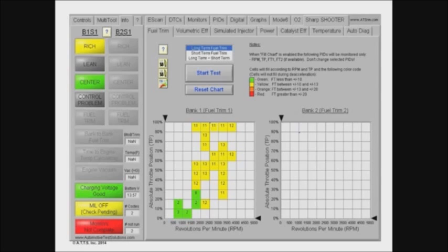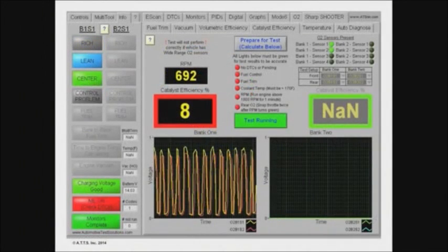Well, we all know how the engine works. We need to take air in, and we need to get exhaust out, right? If we can't get it out, we've got a problem. We look at the catalytic converter at idle. Some manufacturers like GM have done different things. They test it at idle. Some of them test it at 30-some-odd miles an hour going down the road, whatever the criteria is. But what would you say about this catalytic converter right here, right now? Forget about the number. What do you see with the graph if you had your other scan tool? It's mimicking the front. And I'm not doing this. I'm not doing that. That's steady idle, okay?